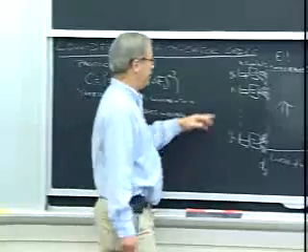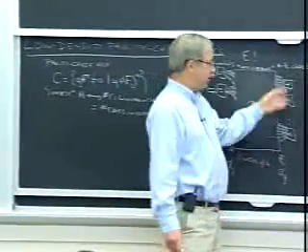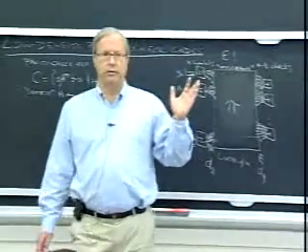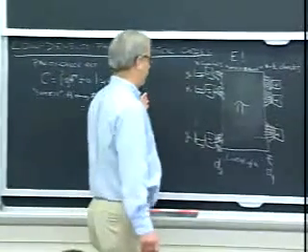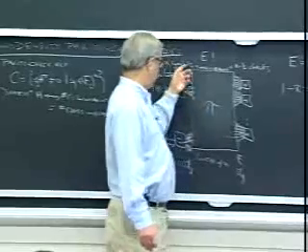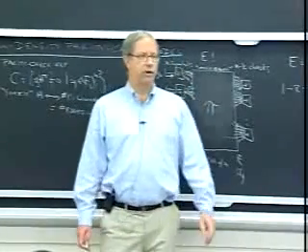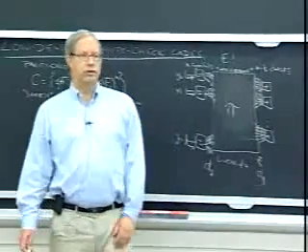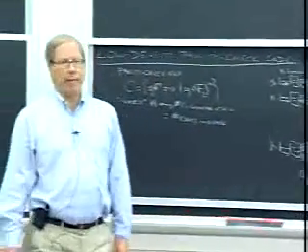And if all those binary values check at all these places, then that's a code word, or that's a trajectory that's consistent with a code word. Basically, everything that's over here then has to be a code word. So whenever all the checks check, just based on hard decisions, you stop.